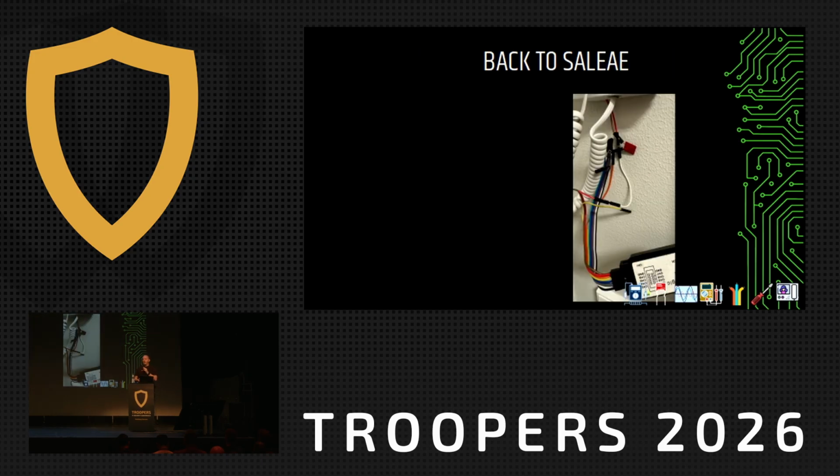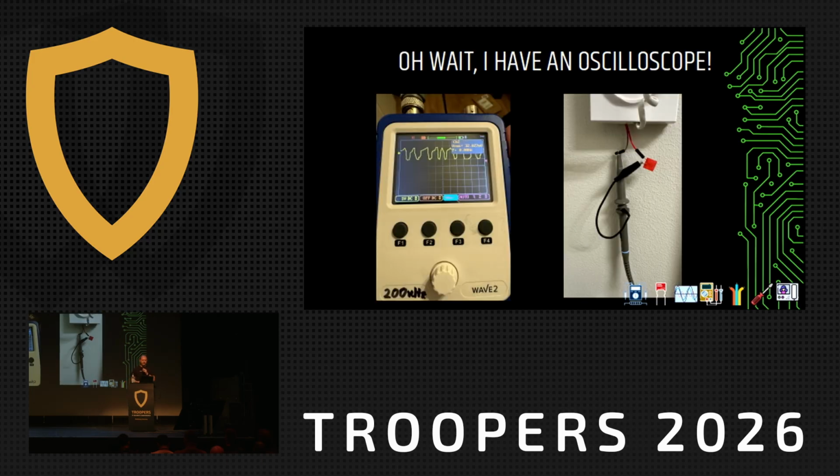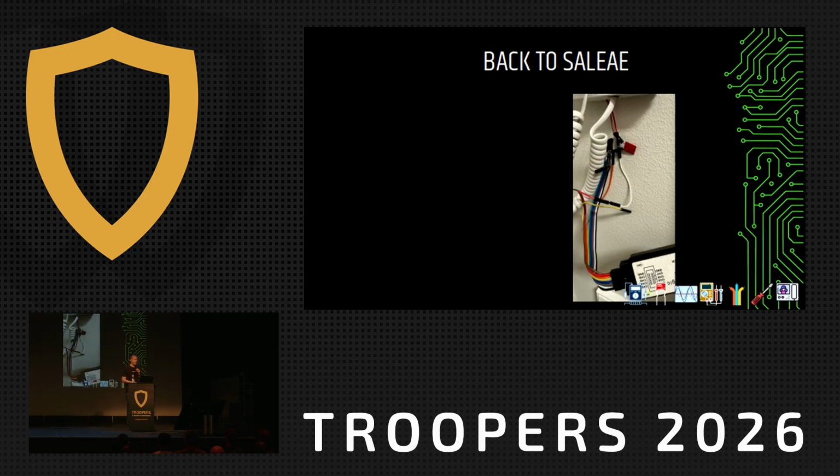So back to Saleae, which then can be used to dump the digital data, right? It can't see the level, but it does have these thresholds, 0.8 and 1.2. And here we can see that it exactly crosses over that level, which is really nice. So we start dumping with it. Anyone of you have worked with Saleae? Yeah, half, more than the pods.